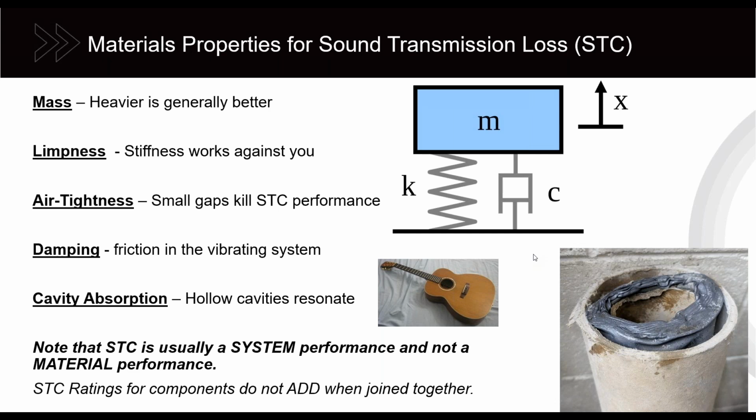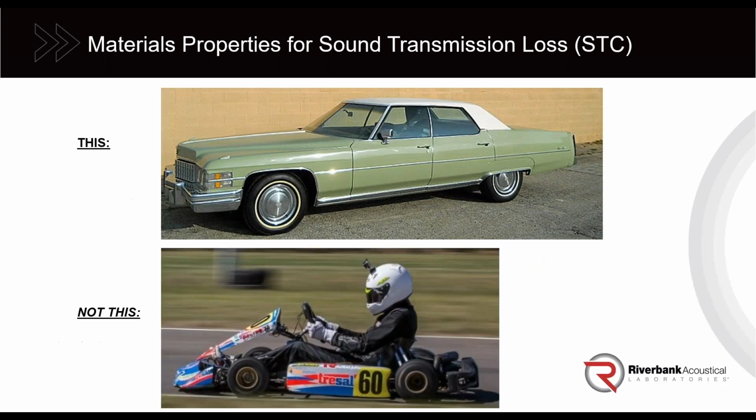So it's very important to note that STC is a system performance and not a material performance. What we mean is you don't have an STC rating for each of the components of a wall. You have an STC rating for the sum total of the wall or the window or any other acoustic system.